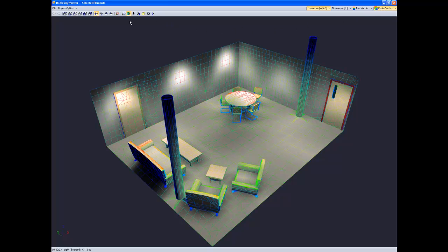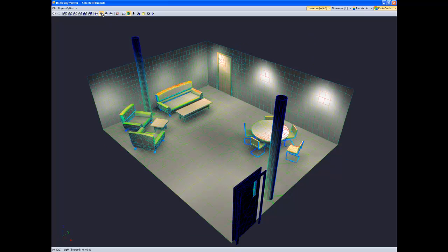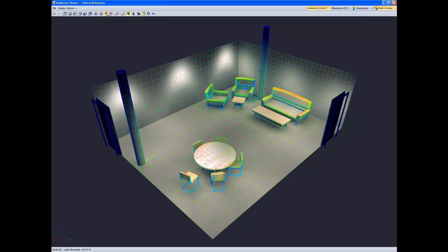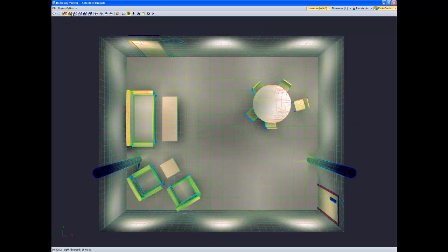Progressive radiosity subdivides each surface into smaller pieces called elements, which receive light. An adaptive process is used to further subdivide the element mesh to accommodate for dramatic gradients in surface luminance.